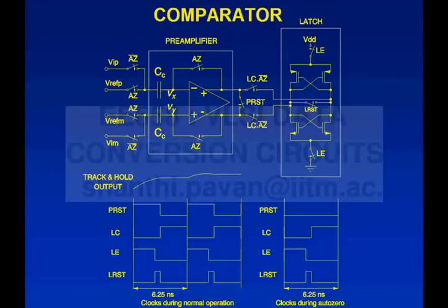If I get rid of this entire part, nothing prevents me from clocking the latch, correct? What do you expect the output to be? See, during the latch reset phase, you're bringing the two together, and then you regenerate. In principle, it seems as if it should stick there, right? Because the two voltages are being charged to the same amount. But that is an unstable equilibrium, and there's going to be a mismatch anyway.